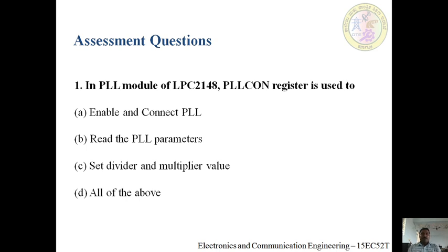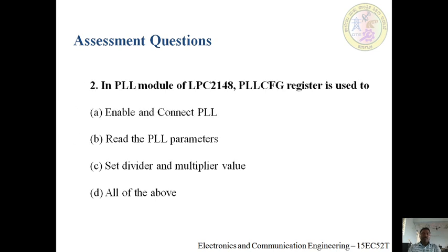In the PLL module of LPC2148, the PLLCON register is used to, as I said already, enable and connect the PLL. In the second question, in the PLL module, the PLL configuration register is used for configuration.